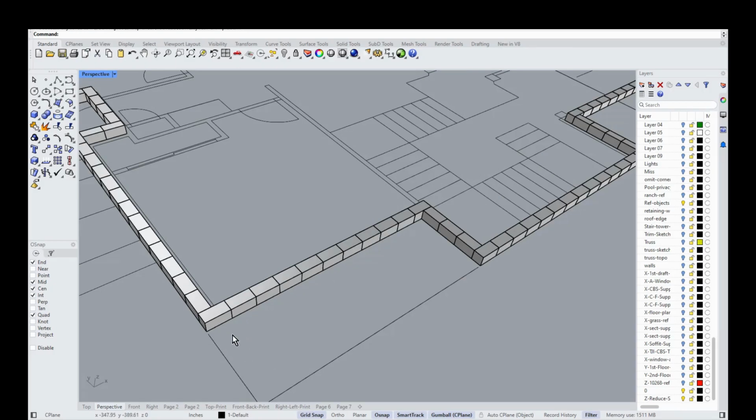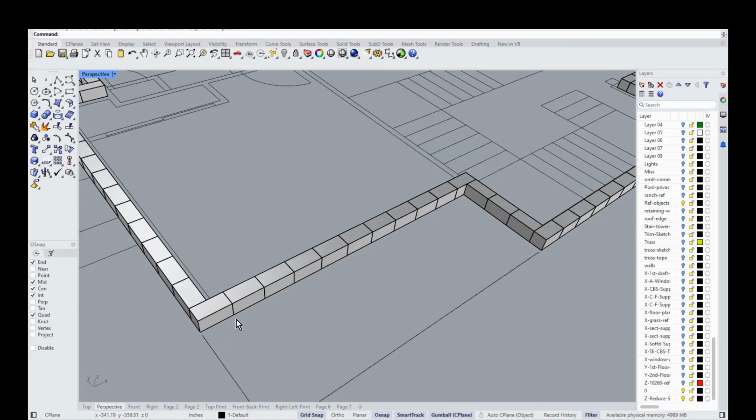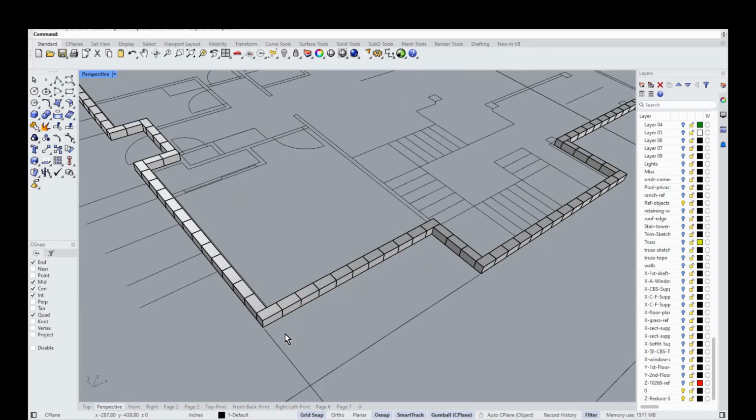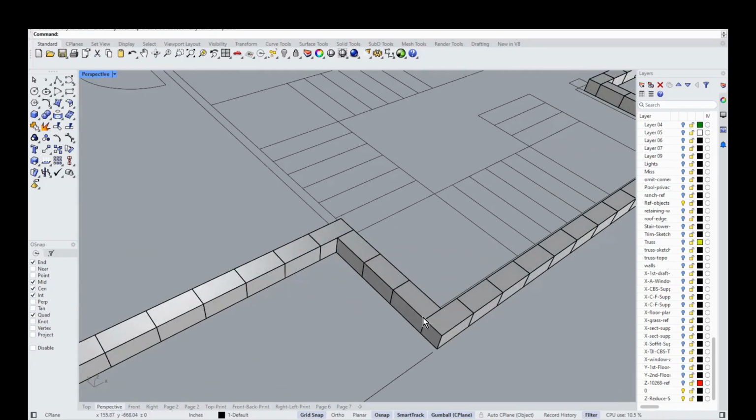So you want to stay on what's called block course, which is essentially an 8-inch grid for position of windows, lengths of walls, heights of walls, doors, what have you. So this is basically like a stem wall that goes around this house, and this is about the simplest you could keep it. But here we can see these 3 blocks going like so, and then it has one on each end. So that should be 4'8" right there on the inside.